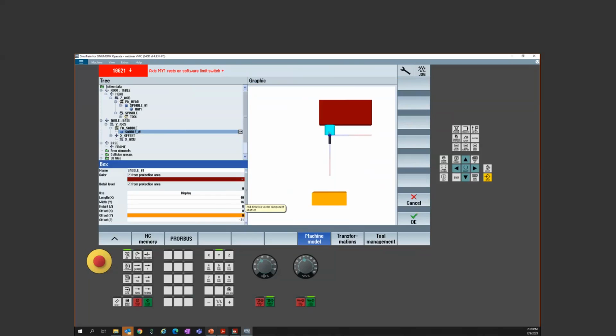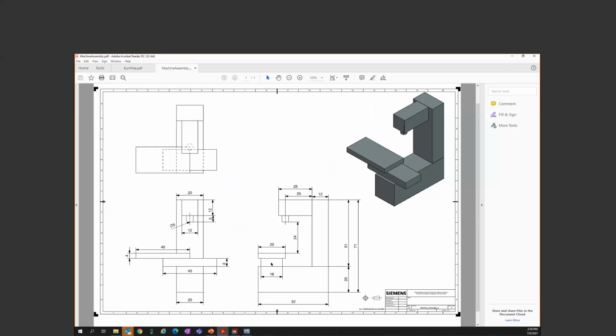So you look at your little design. Hopefully this is driving home the fact that you definitely want to lay this sucker out. So my center line, my spindle is the edge of the table. So I can't offset just 8. It's 8 plus how much this gap is. So if my table's 20 and these are all centered, and that's 16, so that means I have a 4-inch difference. That tells me I have a 2-inch overhang on either side. So if I shift it by half its width plus that 2-inch, so 10, it'll get me right there.